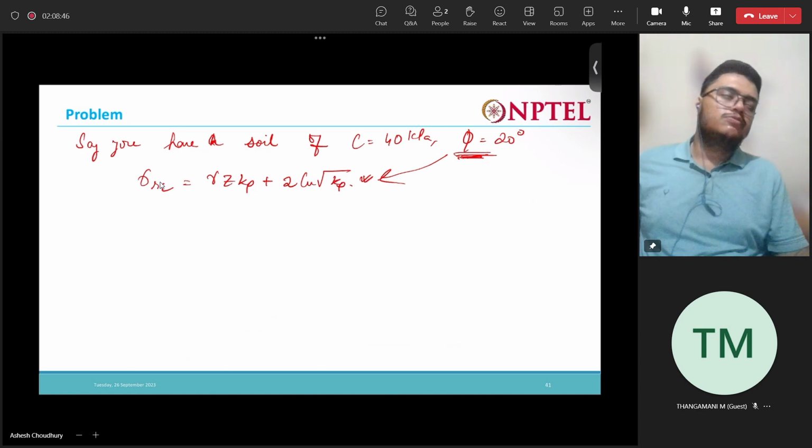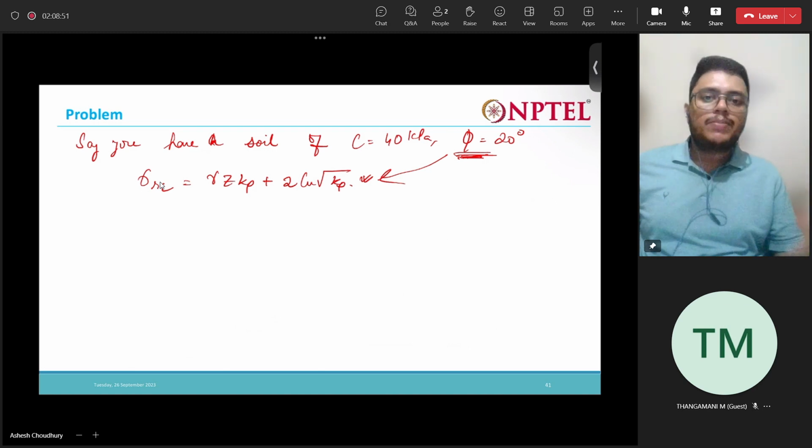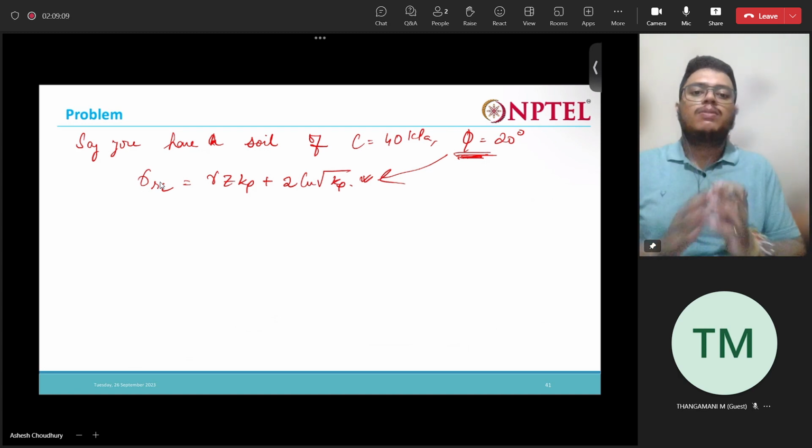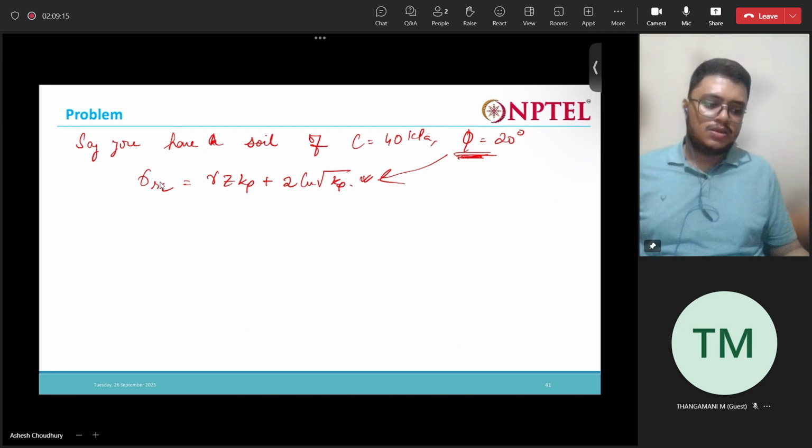Then third, we saw what is the use of vacuum consolidation and how vacuum pressure is beneficial to us. With the use of vacuum consolidation, we are able to get faster consolidation, 90% consolidation in 2 to 3 months. And moreover, we are able to get a uniform isotropic increase in the effective stress, and due to that we are going to get more uniform settlements in the soil.